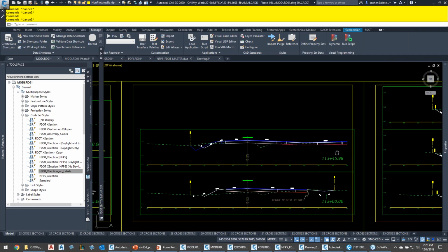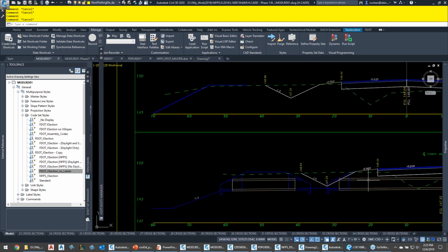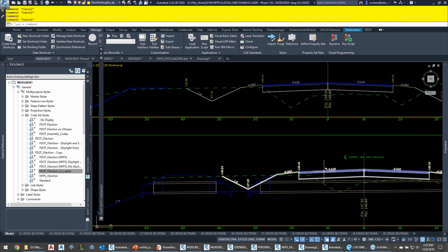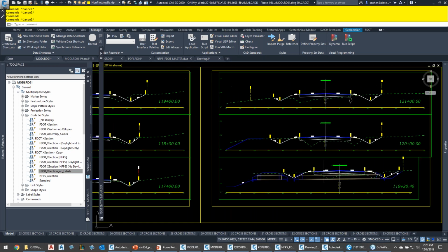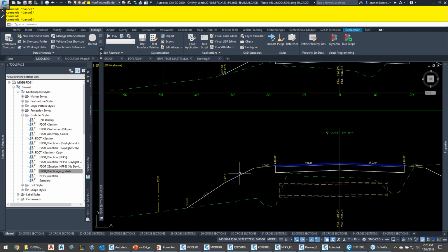One of the other tips I like to show people: there are many times, like if you're in a mitered end section area, you want to turn off and on different parts of your section. Actually, that's not a good example here. I would normally have a miter here and that would do something different. But what I would basically be doing is the pipe would come out here and I would project my own grade. It might be 1 to 6 or 1 to 7 or whatever, because it's going to the top of the miter. So again, many users explode their cross section.